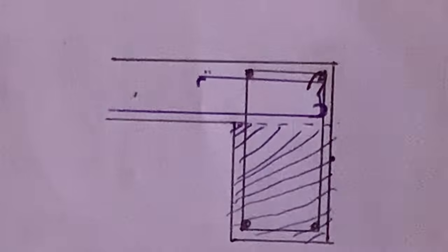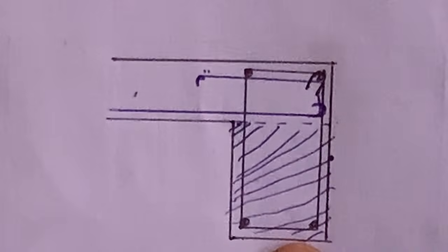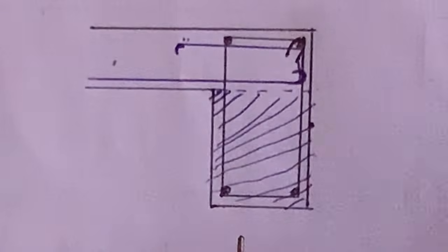As you are doing the reinforcement for your beams, you are doing the reinforcement for your slabs together immediately after you've done all your formwork. I don't know if that makes sense. So when you are casting the concrete for your beams, you will be casting both the beam and the suspended slab or the suspended floor together. That is why this method of measurement works.